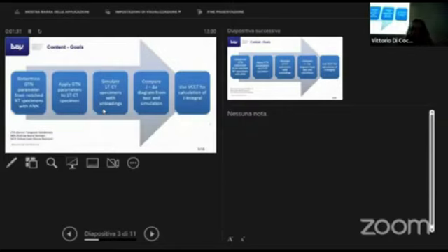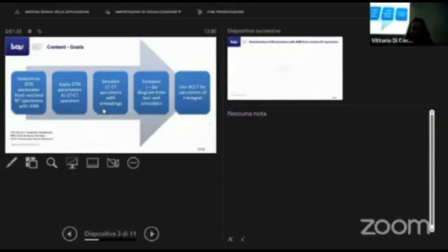First of all, we determine the GTN parameters, which are related to ductile behavior, with notched specimens, where we use an artificial neural network. Thereafter, we apply these parameters for 1T CT specimens to validate the results. Thereafter, we use the unloadings in the simulation, so it could be evaluated with the standard method and the J-delta curves could be determined. We compare them with the testing and they were showing quite good results. And finally, I will say a few words about what is new in our calculation: the VCCT model, where we update it with our thoughts.